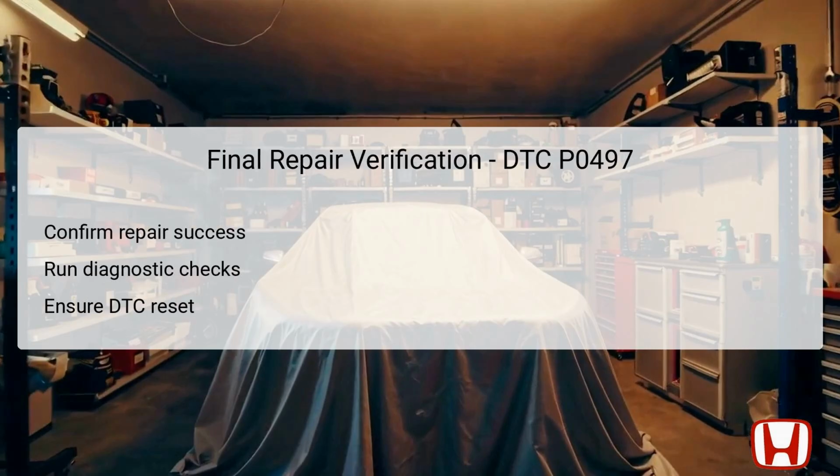After completing the necessary repairs, it is vital to run final verification tests to confirm that the issues related to DTC P0497 have been resolved. Begin this process by conducting diagnostic checks using the appropriate scanning tool. This should include monitoring for any lingering DTCs that may indicate remaining problems within the EVAP system. Once you have verified that there are no new codes, ensure that the previously set codes have been reset.